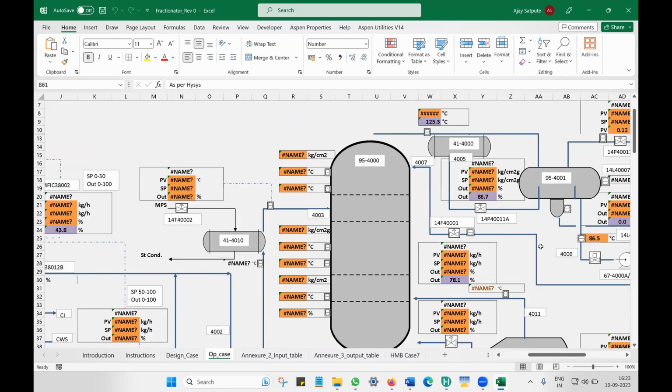First of all, to get more confidence in our simulation model. If you are doing this for, say, several days, and you are getting answers that benchmark with, or match, the operating data, then instead of doing some changes by trial and error in the plant, which nobody would allow, you can change things in the model itself.